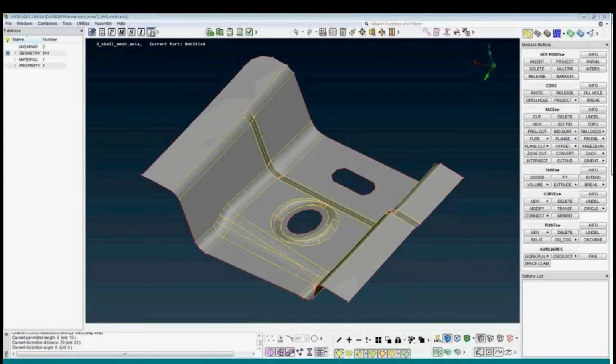In the shell mesh example, we see some of the different algorithms to create meshes. How to set the element length and node numbering, join faces, move and paste nodes, split elements, set the quality criteria, improve the quality of the mesh, freeze areas of the model that are complete, fringe quality criteria, and finally some depth information statistics of the model.